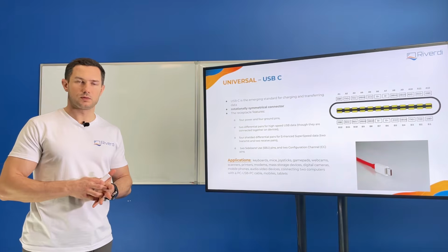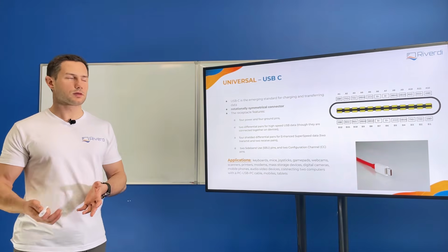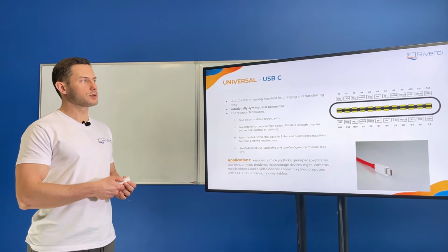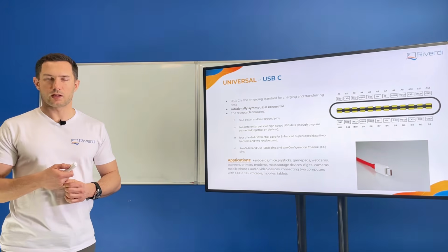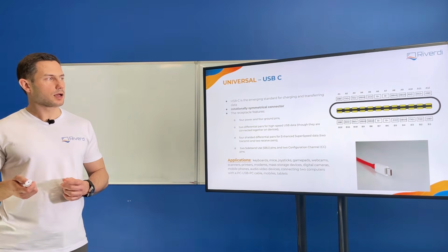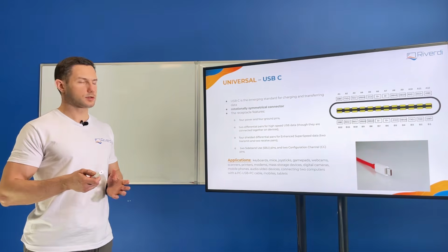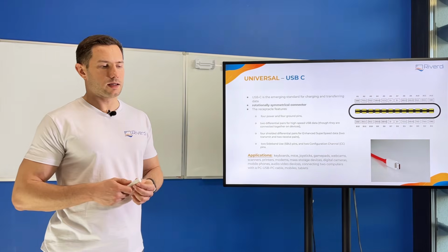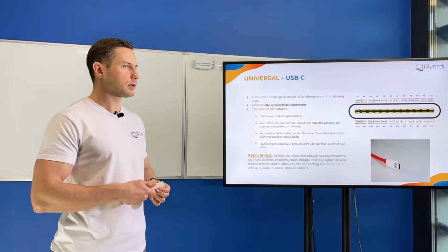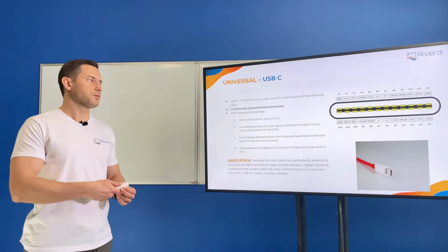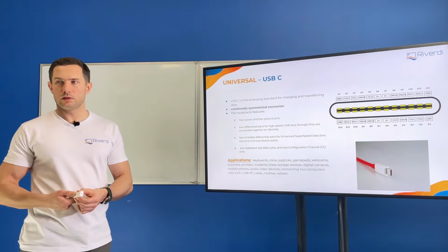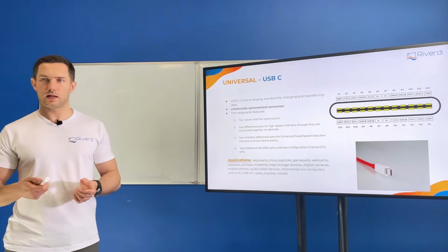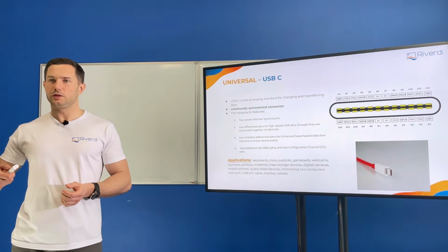Like regular USB, it's usually 5 volt power and maybe half an amp or 1 amp, so a few watts only. For USB-C we can go with the voltage as high as 20 volts with 5 amps in total, so we can have even 100 watts of power. That means this interface is not only for data but a real power transfer, so we can not only charge our phone, but we can charge our laptop through USB-C. So if you buy a new laptop right now, maybe you will not have the regular power connector, but it could be USB-C only.